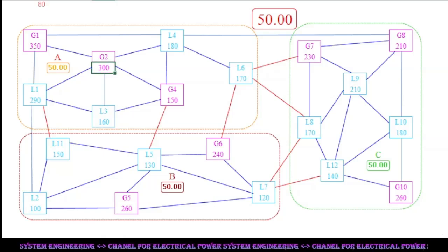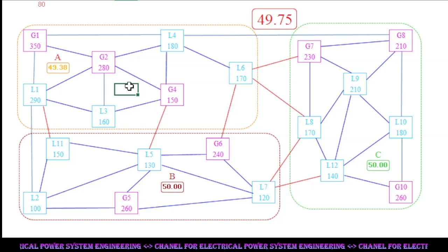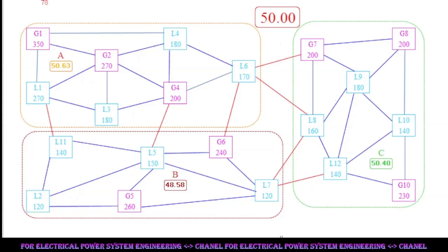First, observing the effect on frequency due to variations of load and or generation within one of the power systems. Frequency drops when generation reduces at any power plant in any system. Mark that drop of grid frequency is smaller compared to drop of concerned system frequency.